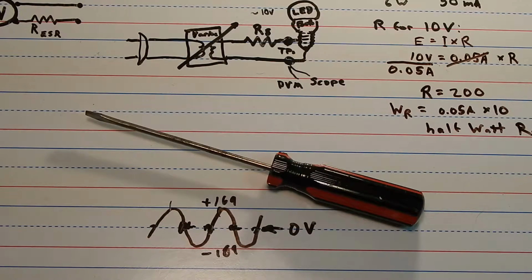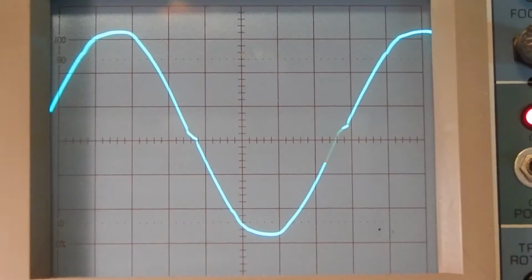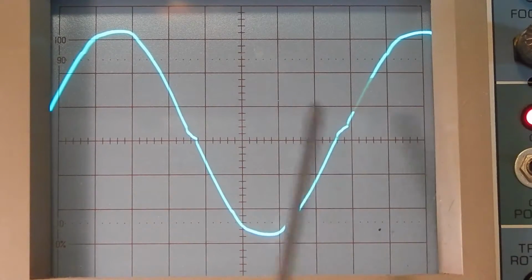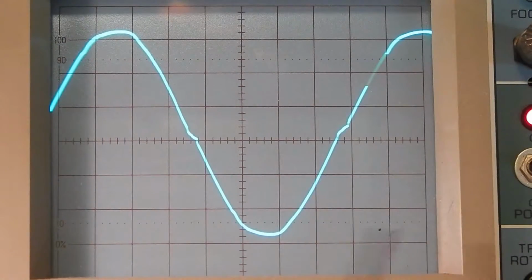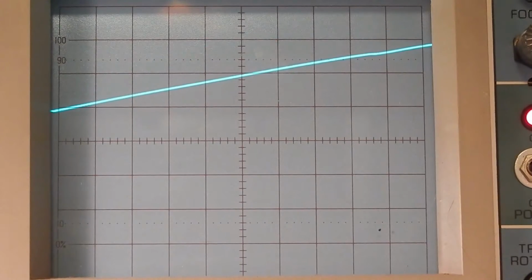I was going to see what kind of interference it generates. So the first bulb I'm looking at is the Cree bulb that gave me so much trouble in the bathroom. And here's the Cree bulb on the scope. You can see the obvious problem here. Right at the zero crossing line, we've got distortion. I wonder if I could go higher in frequency and see it any differently.